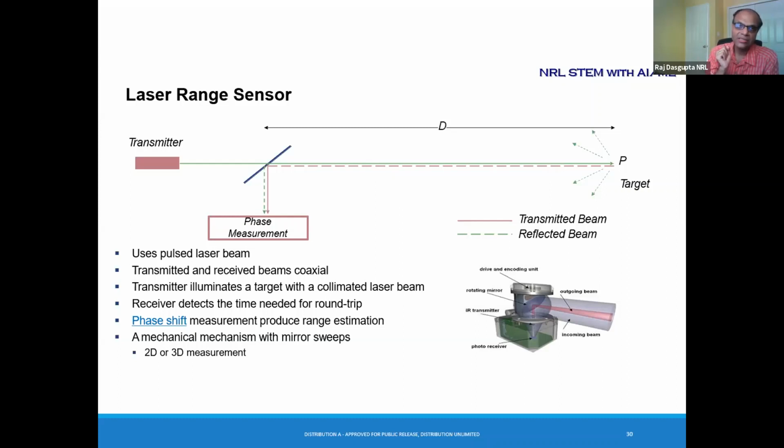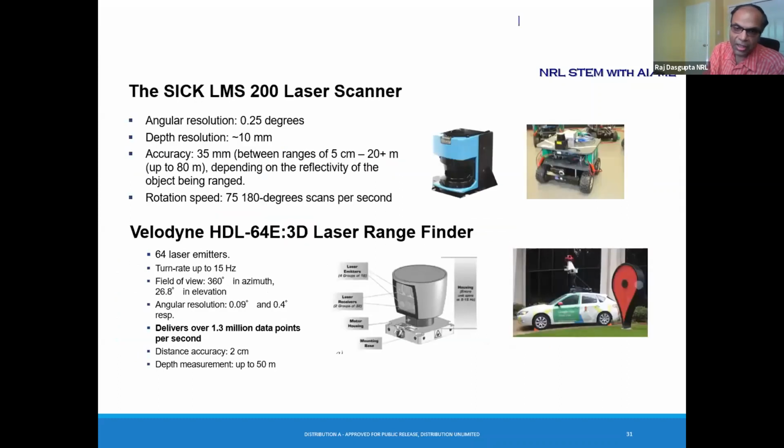There are some advantages of laser as well: the beam angle is much wider than the sound signal, so you can sweep a much wider angle. Most lasers have a 180-degree sweep as compared to the 20-degree beam that the ultrasonic sensor had. Some lasers also have 210 degrees, so you can also see some ways at the back of the robot. Some lasers also have a 3D, up and down sweep. So basically you can get a wide-angle swath, and a view of what is in a wide range around the robot.